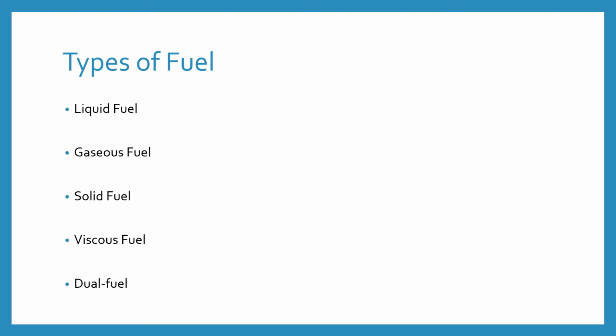Engines use volatile liquid fuel, for example gasoline, alcohol, kerosene, benzene, etc. The fuel is generally mixed with the air to form a homogeneous charge in a carburetor, which is outside the cylinder, and drawn into the combustion chamber of the cylinder in its suction stroke.